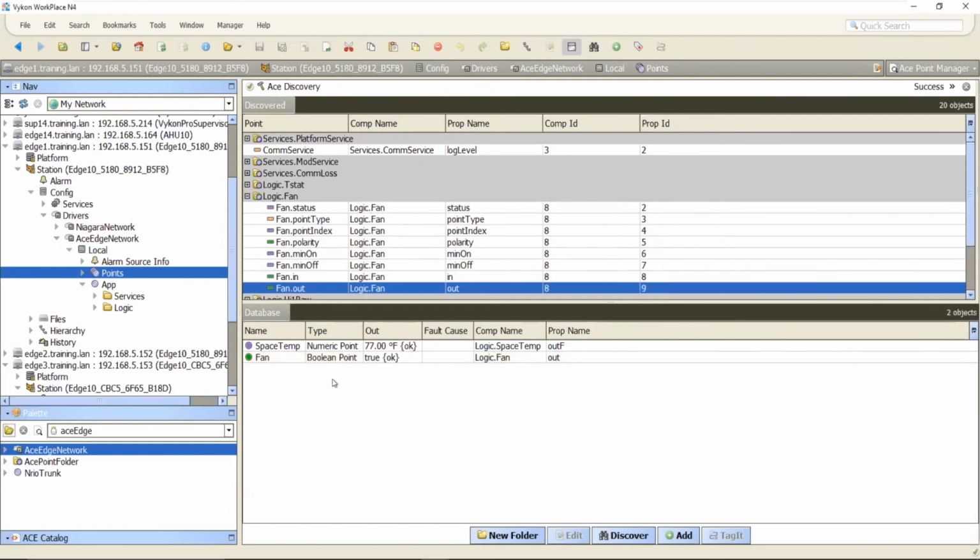And I would be able to do overrides and things of that nature as well. I can bring in the different set point blocks and build a graphic up. So from the Niagara side, you're handling the supervisory level functions like scheduling and graphics and trending, where that C++ engine runs at a very high speed. It executes at a 50 millisecond frequency. So that's why I say high speed, low drag.